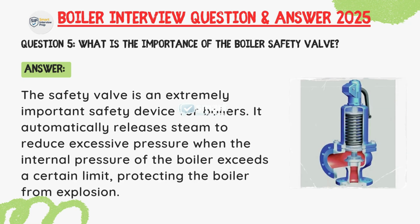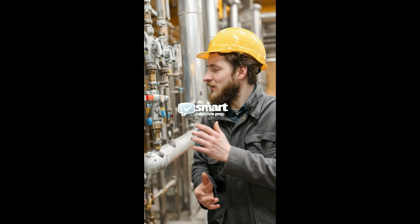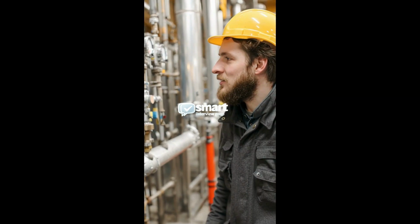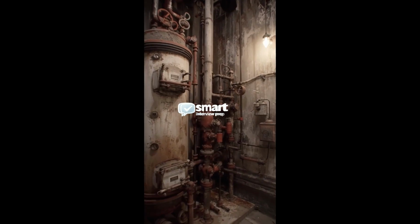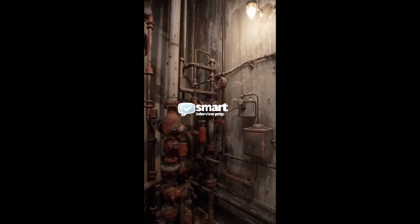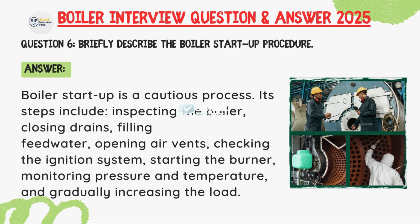Question: what is the importance of the boiler safety valve? Answer: the safety valve is an extremely important safety device for boiler. It automatically releases steam to reduce excessive pressure when the internal pressure of the boiler exceeds a certain limit, protecting the boiler from explosion. Question: briefly describe the boiler startup procedure.